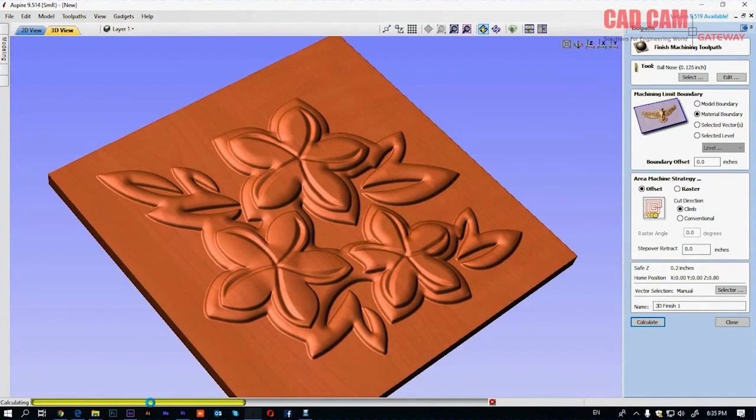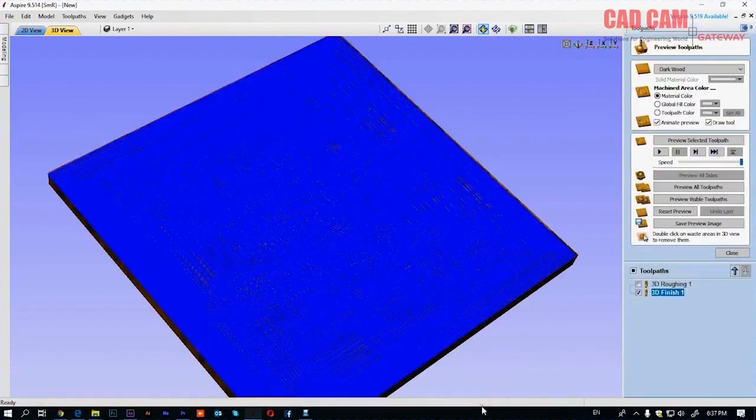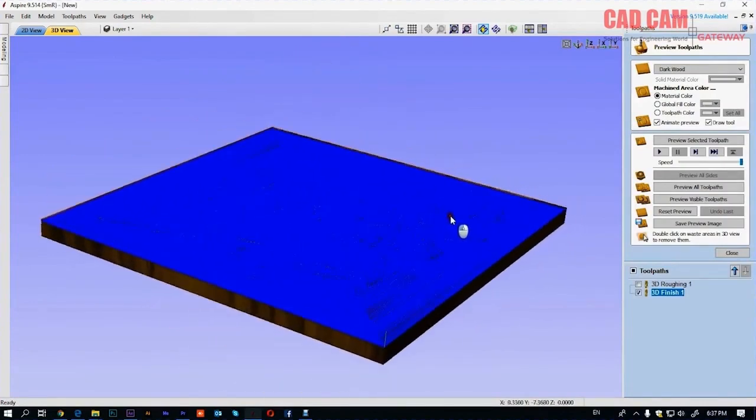Right now, it might seem a bit much to you, but once you get some practice, you'll be able to control the tool passes as well. You can also adjust the radius of the ball nose as you wish. So viewers, as you saw, it took some processing time. And after that, these are the tool passes. After this, the tool is practically ready. The pass has been generated.